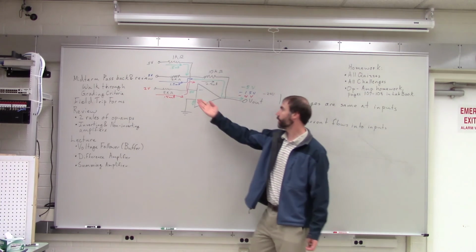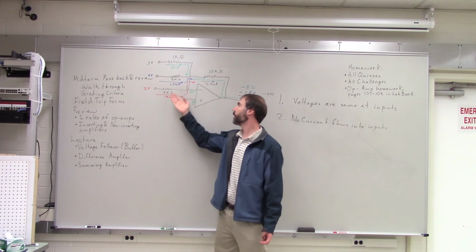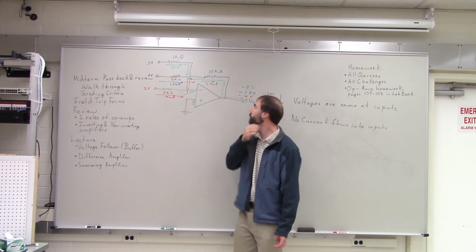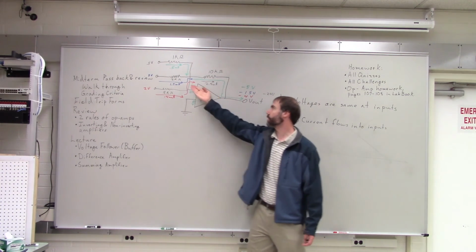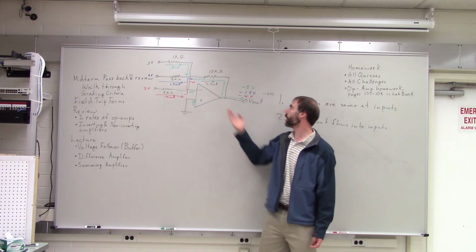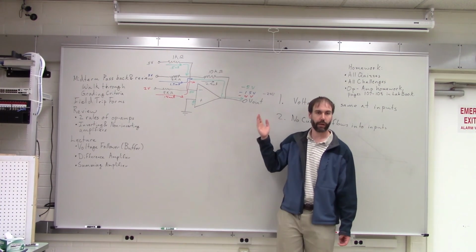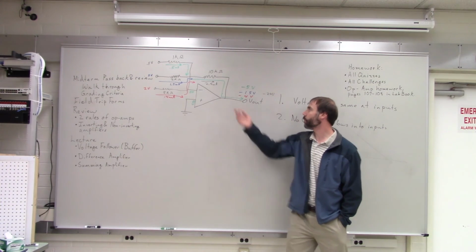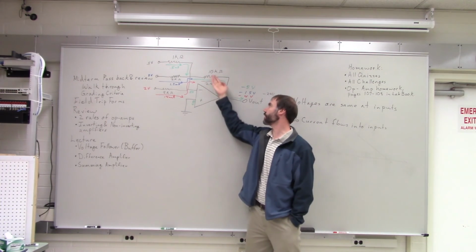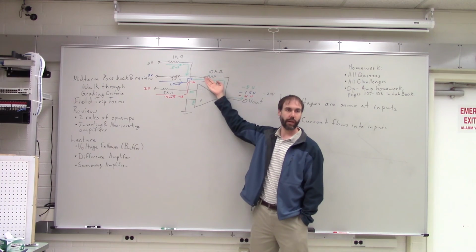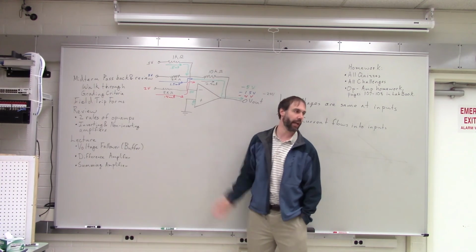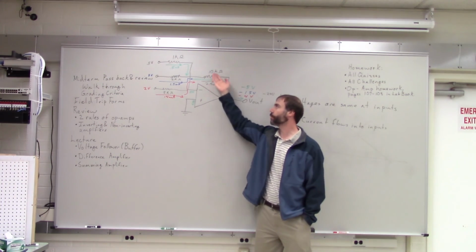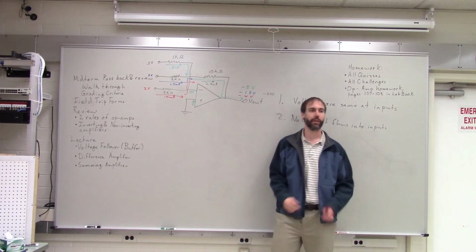So that would change the volume on each of these audio tracks, right? Less resistance would mean more gain, so that would be a higher volume for that track. And then we could have an adjustable resistor here as well. And if we change that, that would change the gain on all of the tracks. So this could be like the total volume for the entire thing, okay?